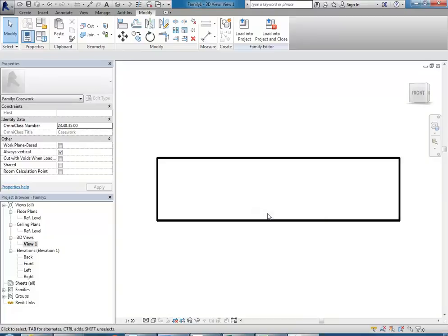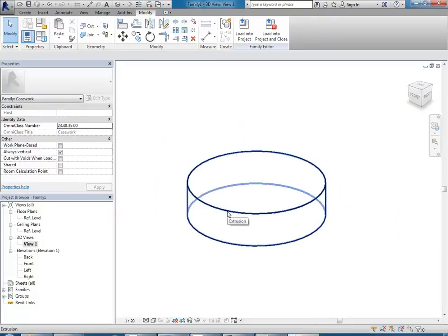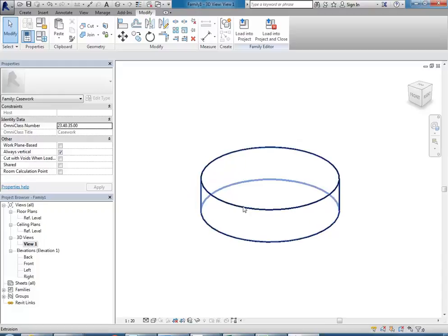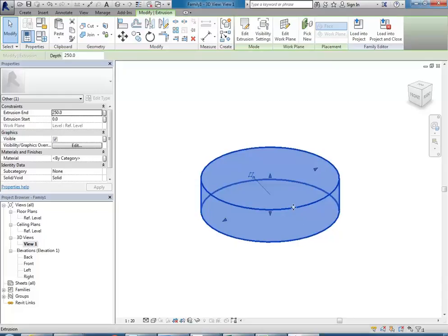Going to fit everything in the drawing space into that view. So orbiting, and there we are. So it's a problem. Most of those families, they're zoomed into some strange area. You just have to do that when you first make them. So there's my extrusion. The height is, I don't know, the default 250. So I'll make that a bit more, 400 or something.